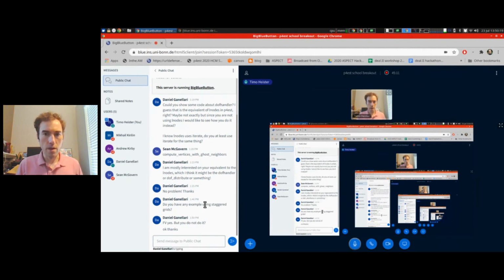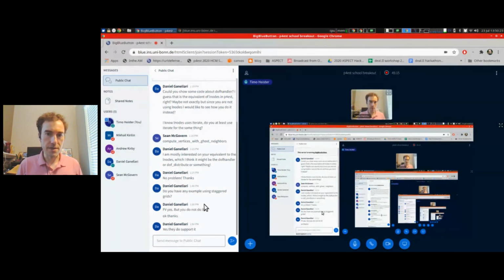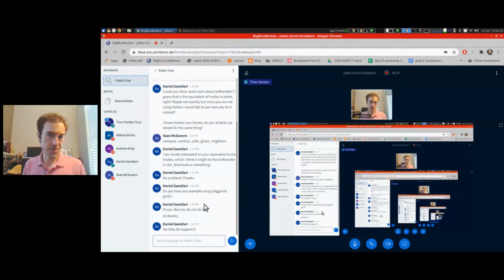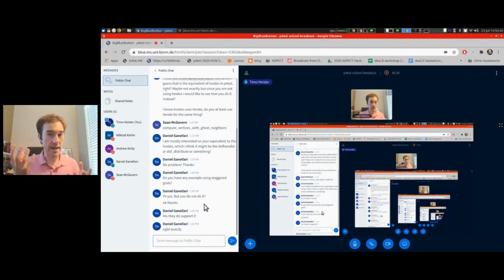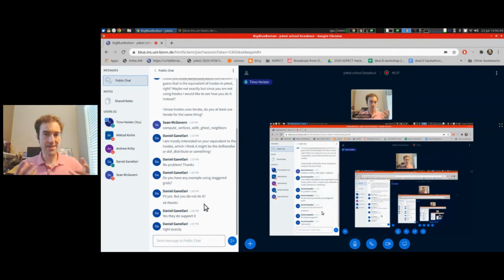So yes, in finite volumes you kind of also have this, but in finite elements, you define different finite element spaces. So think of, for example, a staggered grid for a Stokes problem where you define the x and the y velocity on different shifted meshes for a staggered grid for finite differences. For finite elements, you use a correct higher order polynomial space that would be kind of equivalent to this, but more flexible to arbitrary meshes, curved, whatever. So we don't do that at all.